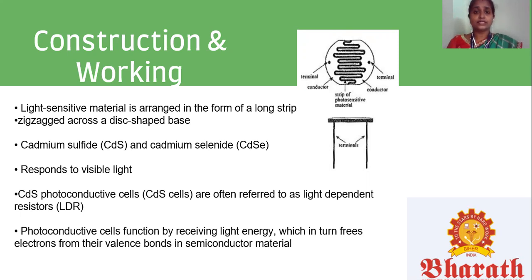As with all the other devices, care must be taken to ensure that the power dissipation is not excessive. For visible light, for the cadmium selenide cell, the spectral response is at the longer wavelength end of the visible spectrum and extends into the infrared region.